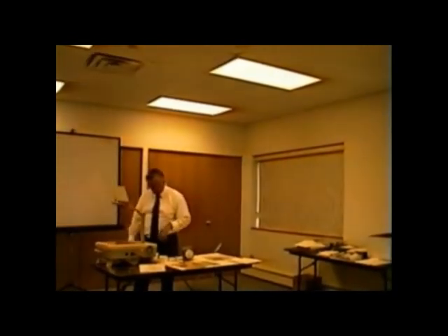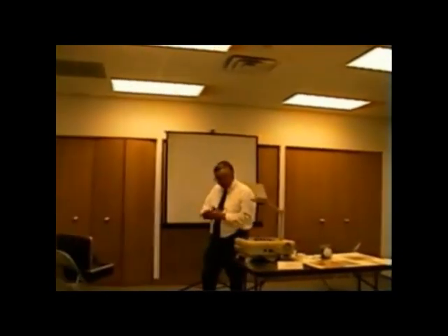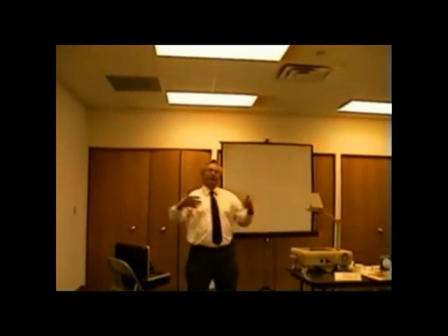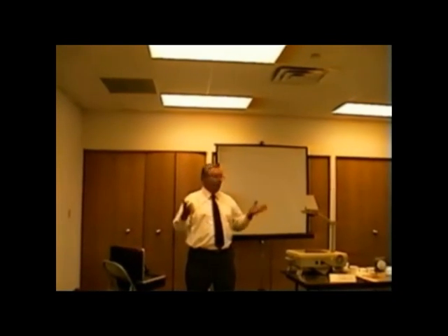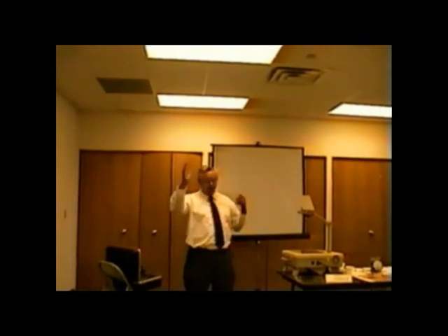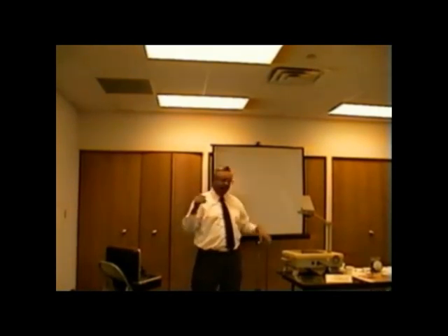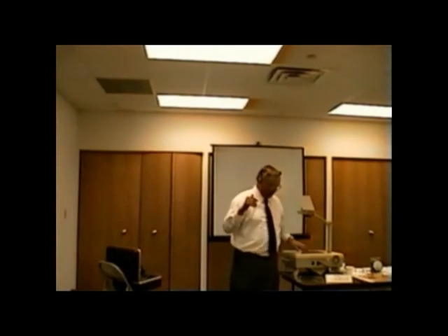Now, watch this. We'll come back here now. When you start looking at the modulating training manual, you're going to see furnace blower specifications that go all the way up to 0.8. But that's a different kind of blower. It changes its speed depending on the static, but 0.8 is maximum on a modulating. But on a conventional furnace, and you look at all furnaces, they will all have the maximum external static pressure.